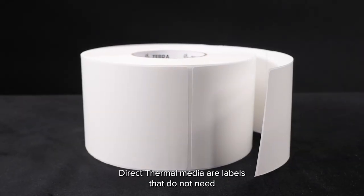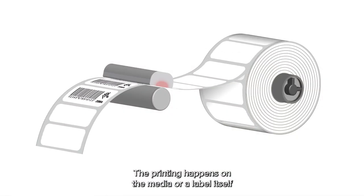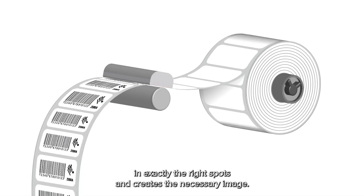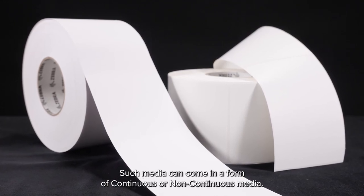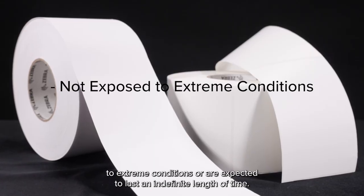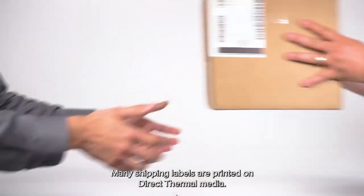Direct thermal media are labels that do not need any ribbon to produce the image on them. The printing happens on the media or label itself when it contacts the heated printhead, and a chemical reaction darkens the media in exactly the right spot and creates the necessary image. Such media can come in a form of continuous or non-continuous media. Direct thermal media is a good choice for labels that are not exposed to extreme conditions or are not expected to last an indefinite length of time. Many shipping labels are printed on direct thermal media.